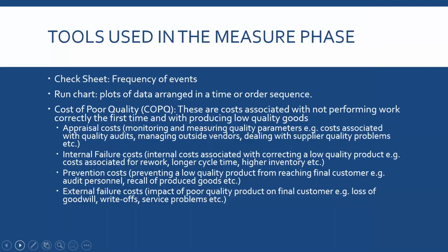Okay, so starting with the tools that we're going to use to collect the data, it's a simple tool. We call it the check sheet, and the check sheet is basically a tally sheet where whenever a problem or a defect happens, we make a check mark. We say, okay, here's problem number one happened now. So we start checking the marks in order to have some tally checks on each